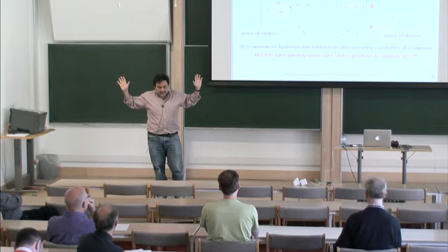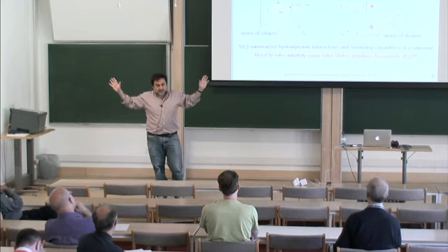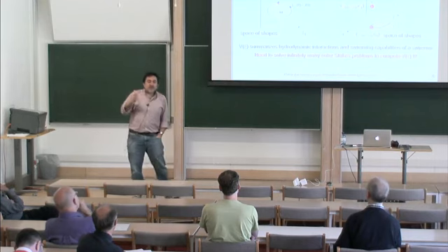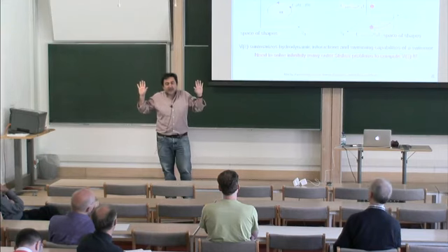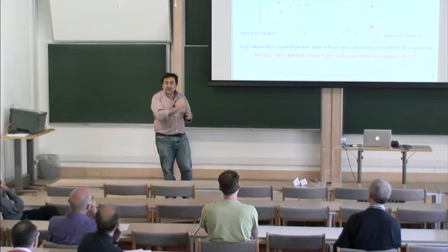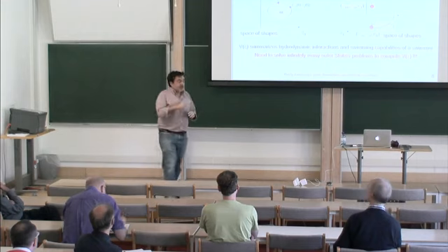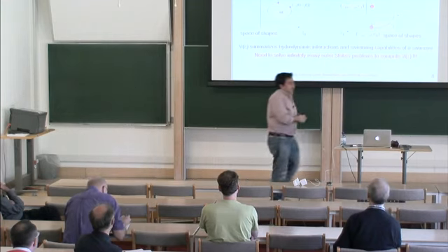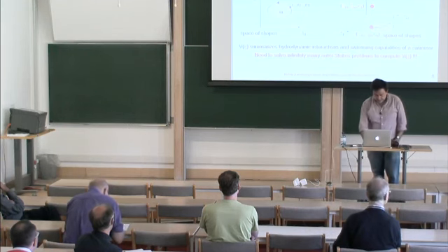You give the boundary data, you compute the stresses. What you have to do is know the sensitivity of this map with respect to shape changes. Conceptually that amounts to knowing the solution of the outer Stokes problem for any geometry. So it's an infinite dimensional thing. You have to know the analog of Stokes formula for this system for any shape. So it's computationally very intensive. We have done it brute force, so to speak, but there's a lot to be improved.